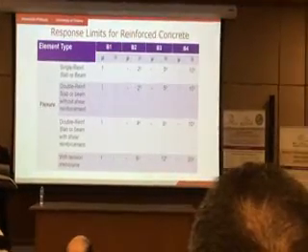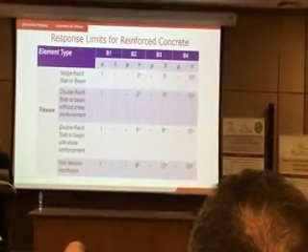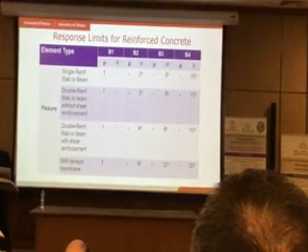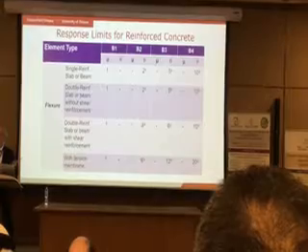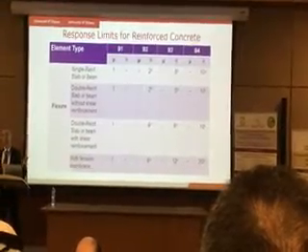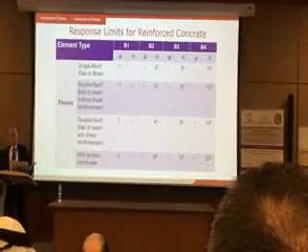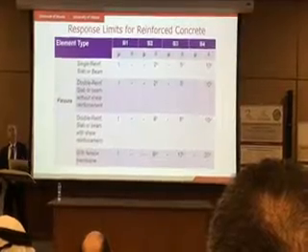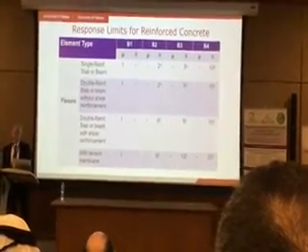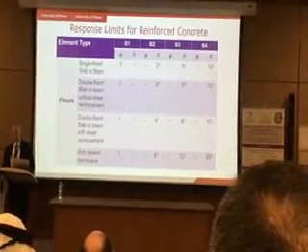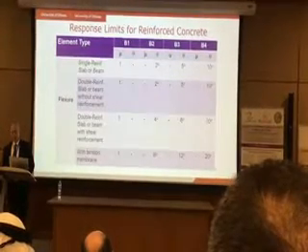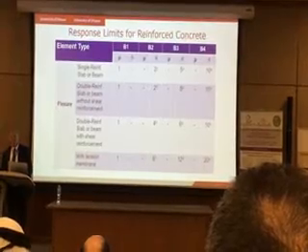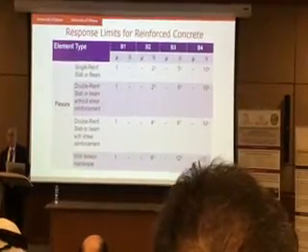But in blast, because they look at glass windows, they look at doors, they're not security. The whole profession evolved from security people, not from structural engineering people, and that's why they started using support rotations. Support rotations are used under high displacements, so it's either ductility or support rotation that is specified in the CSA standard.